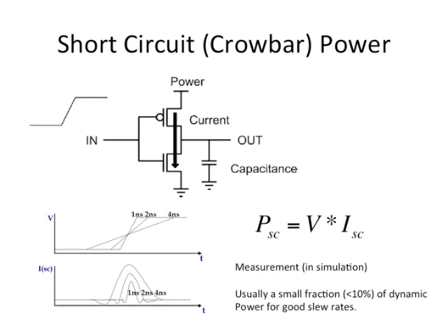Before the output can react and come down, the PMOS gate is shut off. So I don't have much short circuit current. So actually this is a correct representation of what is happening. The peak value of the short circuit current will also be a function of the input ramp.